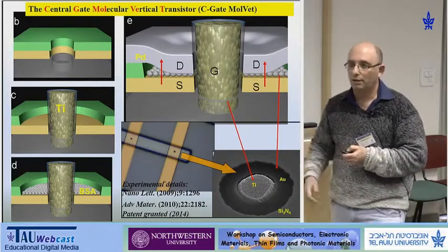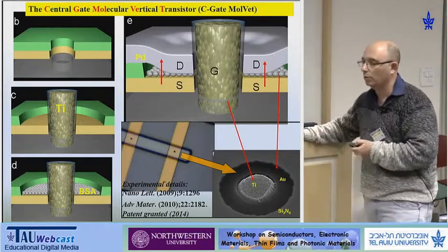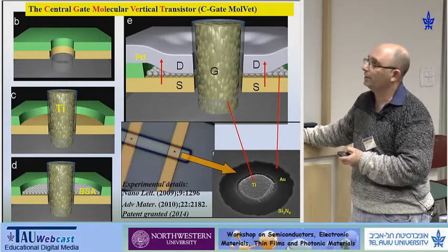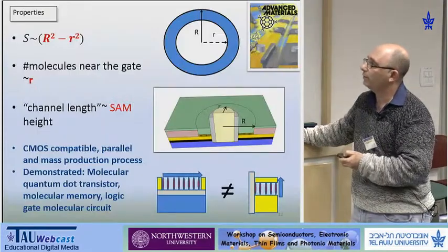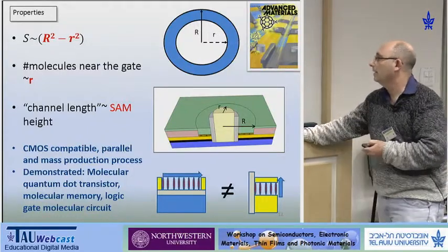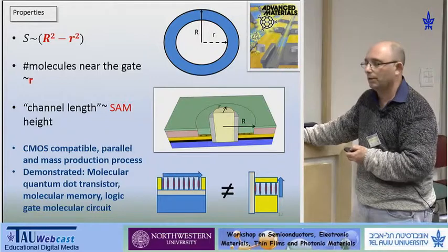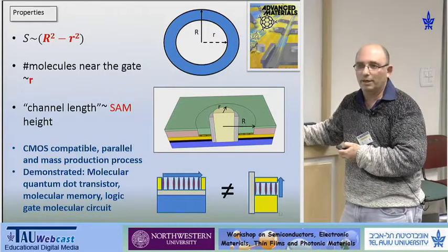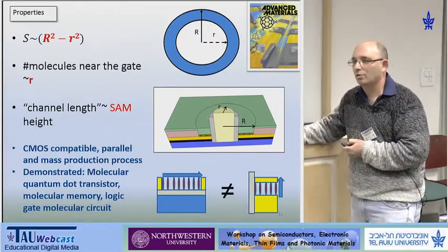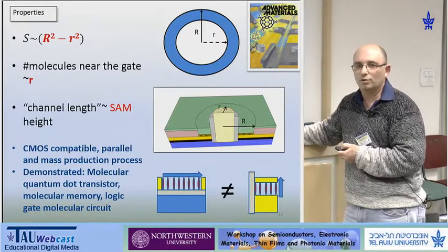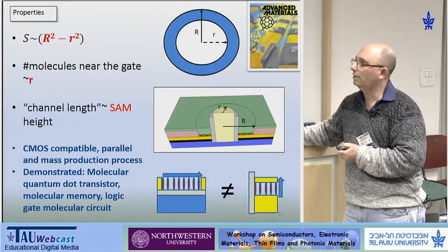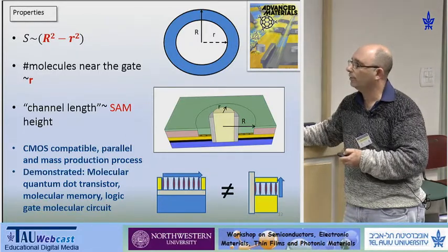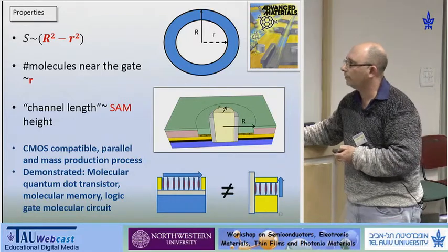So how can we apply it to bioelectronics and molecular electronics, and how can we prove that this works? So let me show you some examples. Before this, for those of you who are interested in fabrication details, this is a fully photolithography and CMOS compatible technique. It means that we can make a sub 10 nanometers channel in a photolithography technique. We don't need any e-beam techniques, and it is CMOS compatible if we use the right molecules, and it got some interest from several microelectronics companies.